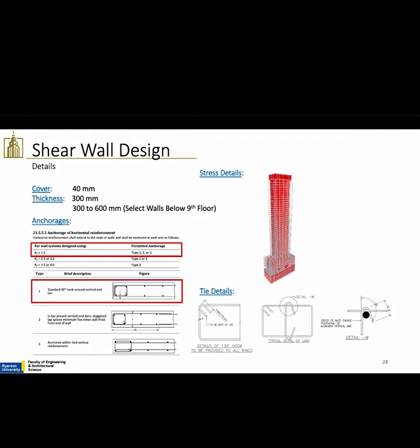Based on our analysis, the stresses in the shear walls are almost exclusively in compression, with negligible tension between the middle stories of the high-rise structure shown in this image. While the upper stories experience considerable tension stress, this is because the code requires large lateral forces at these top stories. And since there's minimal gravity loading up here, certain load combinations will produce quite a bit of tension.